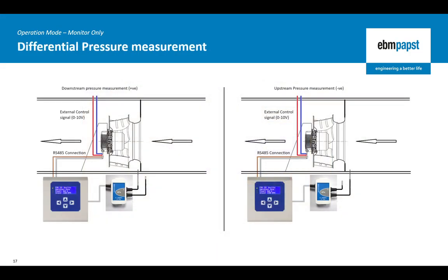The addition of a pressure transducer also provides the capability to measure system pressure. This can be either the negative pressure that would be present in the upstream suction side of the array, the positive pressure in the downstream exhaust side of the array, or the differential produced across the upstream and downstream sides of the fan array.